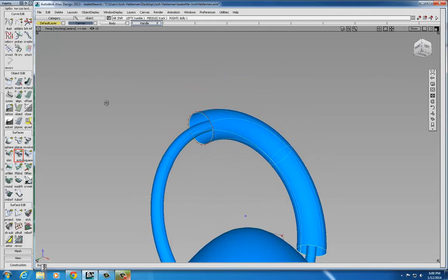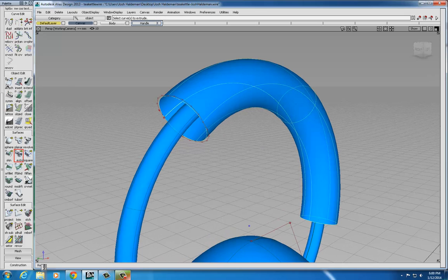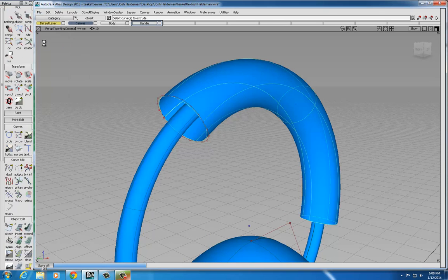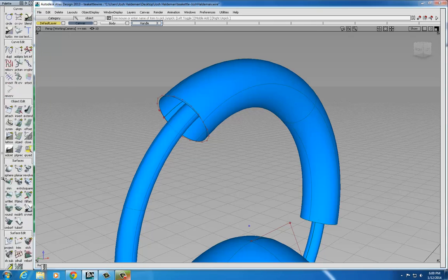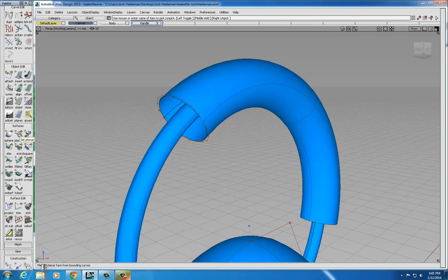And so I'm going to fill those in, again, using the planar tool. Hit File, Save here to save your progress so far. Go to Pick Nothing, Pick Object. Scroll down to the Surfaces menu and choose the Planar tool. Then pick the edge of the object here, and you'll notice that it'll give you options. You can pick either the circle or the extrude. You want to pick the extrude because you want your planar surface to align with the edge of the geometry that you created, the surface here, not the original circle, even though they are actually the same shape right now. You can only do one of these at a time because the complete selection has to be planar.